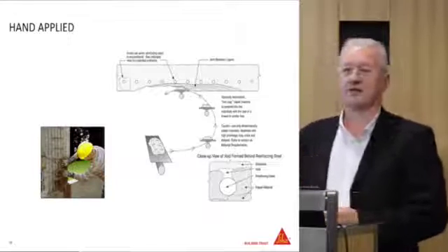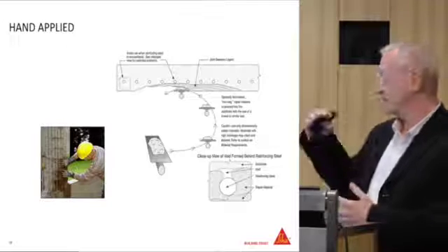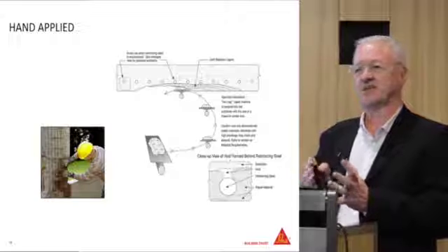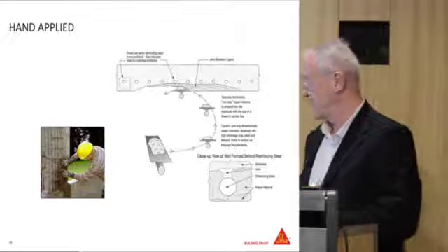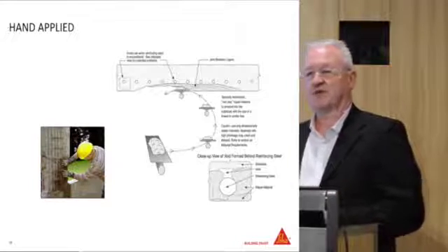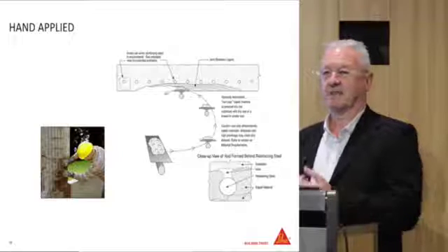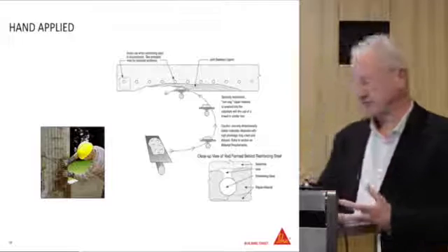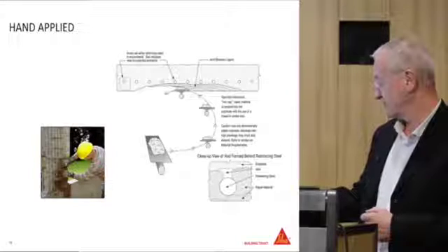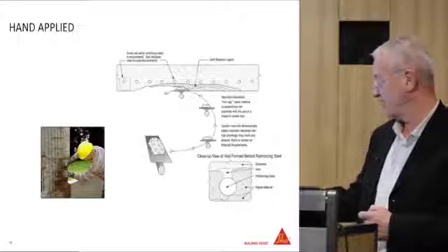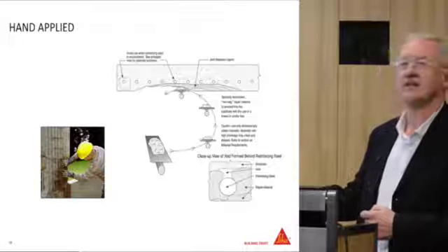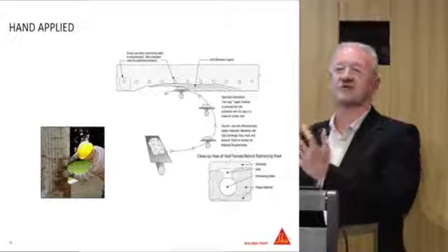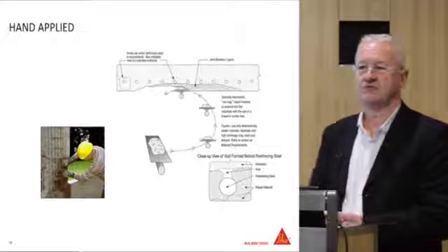That's all very well if you've just taken the top surface of the concrete off, but when you've got reinforcement exposed, it's a little bit more difficult. So what you have to do sounds pretty basic, but you literally have to use your hands and force the material behind the reinforcement, trying to avoid voidage behind there as well, because you really want that reinforcement to be fully encapsulated in the repair mortar, because then that also repassivates the reinforcement bars.